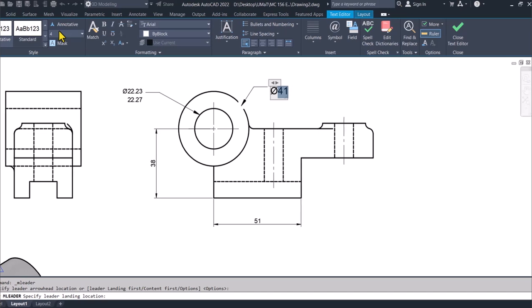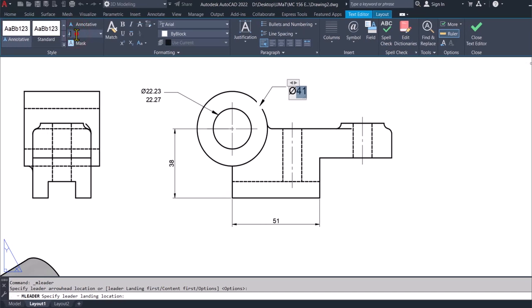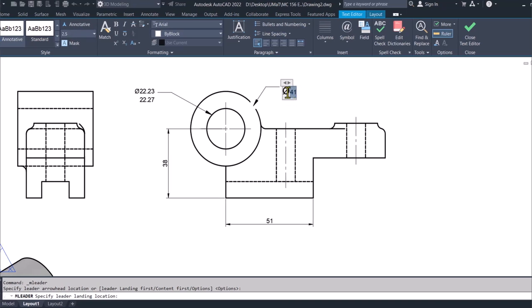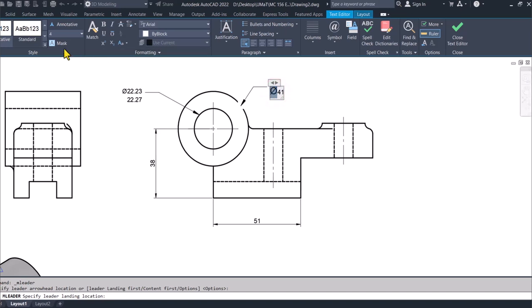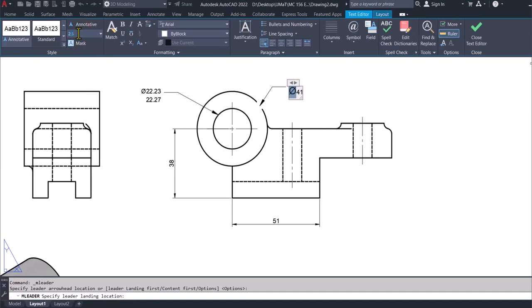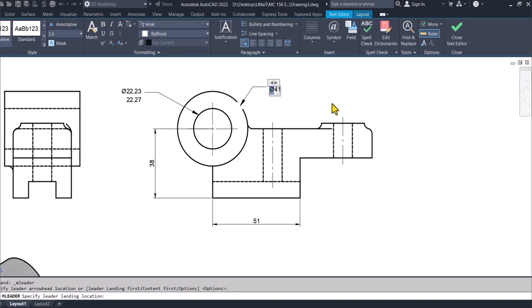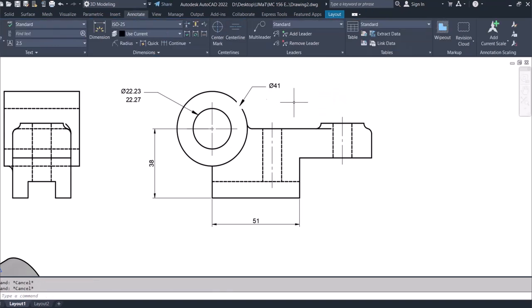Now let's select that and then maybe change that height there to maybe 2. Same for the symbol, to make sure we've changed it to 2. Okay, now you see it looks like this part is broken. It's just the software and the graphics card misbehaving. So we type region and it will regenerate that for us.